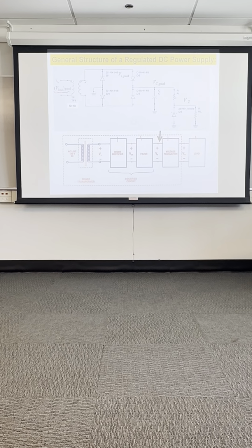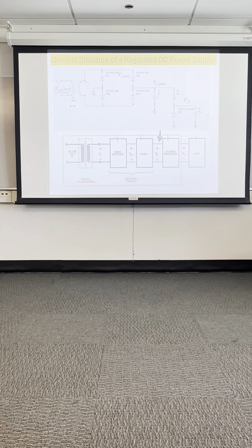So if we're paying attention now, later when we cover this circuit in lab 1, we'll recall that this circuit uses floating inputs, which means you can't measure the voltage across these two terminals with a multimeter because it's a differential input, so they're not referenced to ground. So just keep that in mind later on.